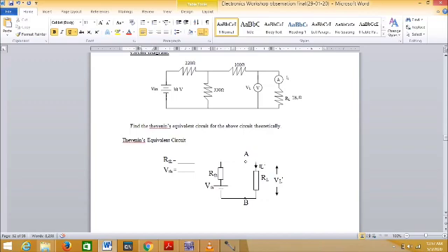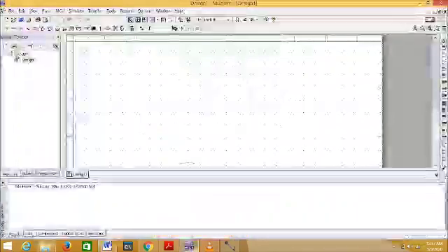Later on, you need to connect this Thevenin equivalent circuit. After connecting this Thevenin equivalent circuit, you need to determine IL dash and VL dash. Thereafter you need to calculate the percentage error. See how I am doing. You could observe that there are 4 resistances, right?